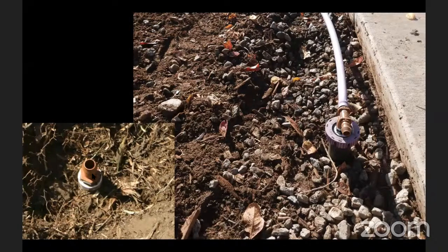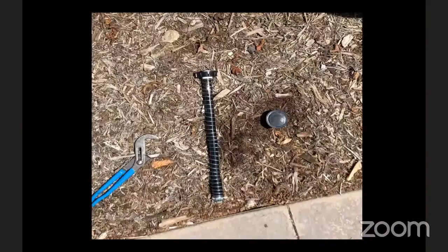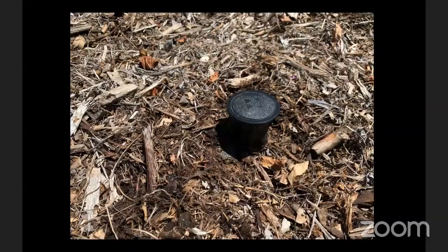And then on the other side of that adapter, there's the barb that your drip tube slips over and secures on. And then for capping, it's similar: you take out the guts of the sprinkler, and make sure you have the little rubber gasket that's in the bag with the cap, insert that into the cap, or lay that in the cap, and then screw down, and you'll get your watertight seal.